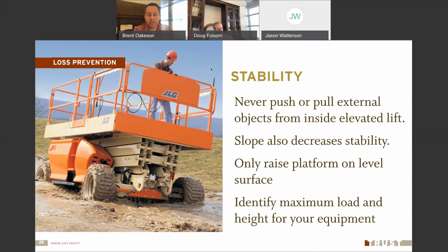So watch your slopes. That can decrease your stability. Just a slight slope when you go up vertically becomes a lot more off the center of gravity, higher in the air. So watch for that. Only raise your platform on a level surface.